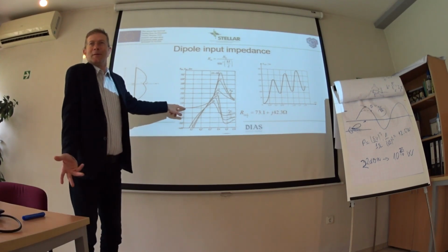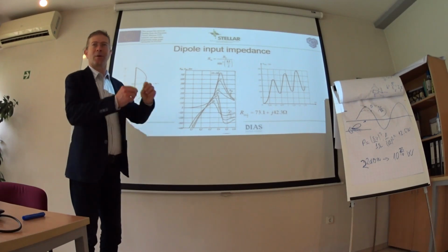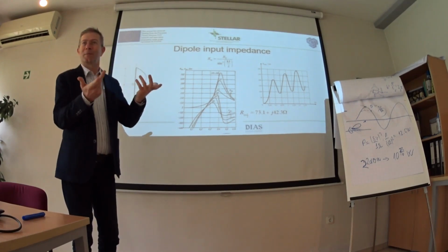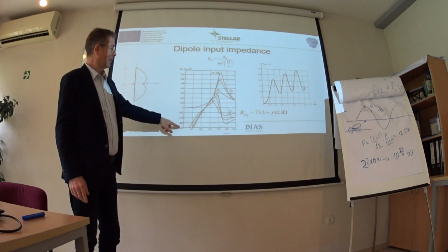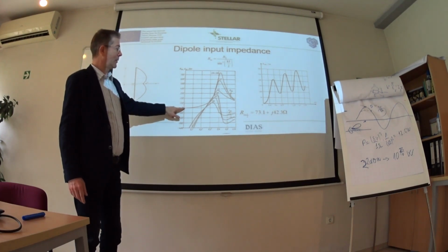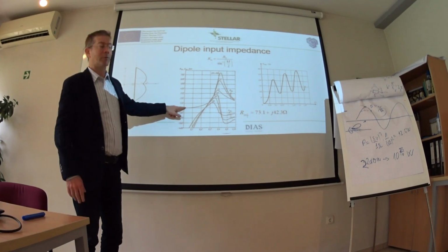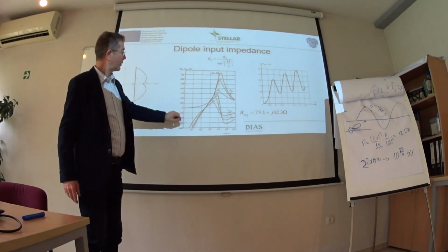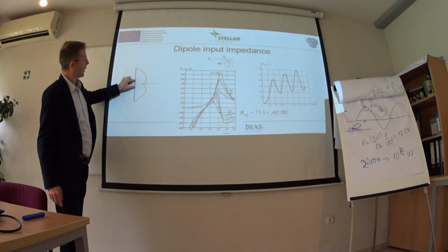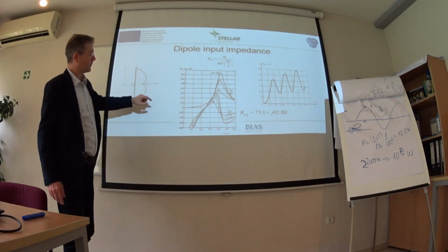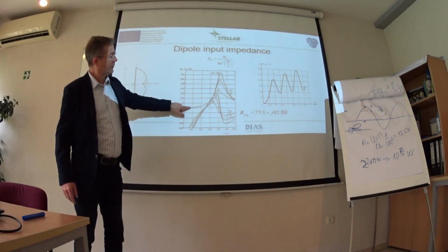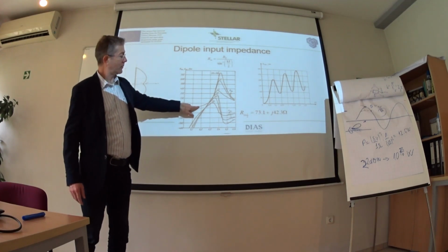So it basically doesn't work. That's why a very short antenna doesn't transmit. Input impedance is low, radiation resistance is low, which means that nothing goes to the free space. We start to increase the length of the arms, and some impedance starts to show up.